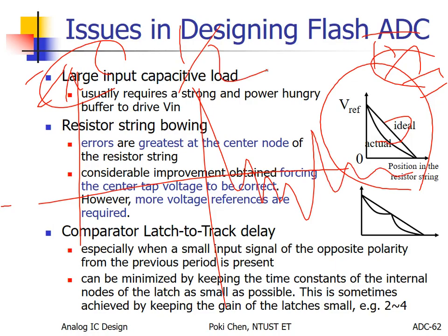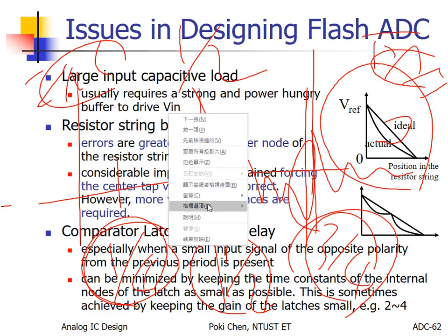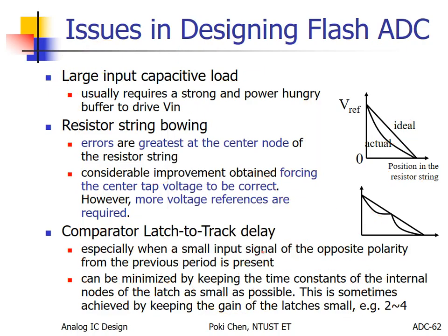And for the second largest, usually 3/4 or 1/4. This is dominated by the MSB, and these others are dominated by the second MSB bit. Anyhow, that is the usual case. In the middle, usually you get the maximum INL.